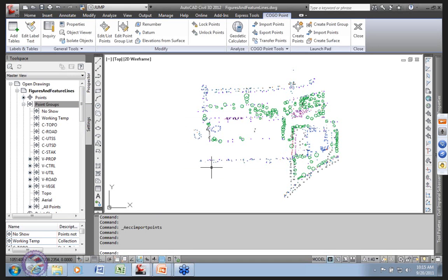And description keys do a lot of that before activity. For a description key to function, there must be a COGO point or a point feature in your drawing. The other thing that's important to recognize in terms of Civil 3D is there is no such thing as a point.